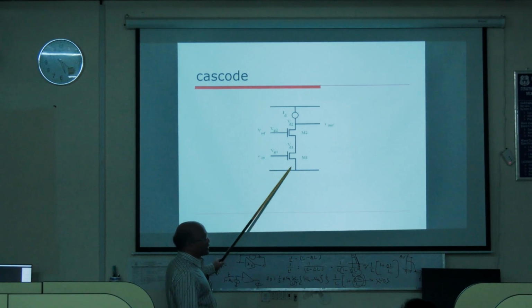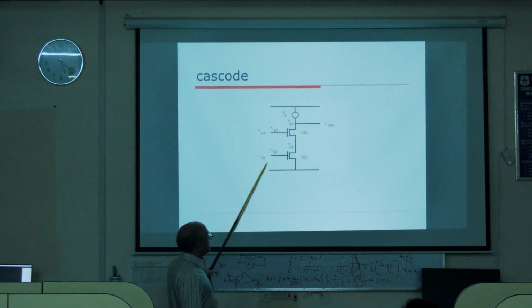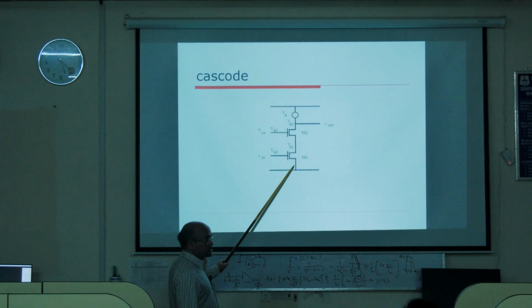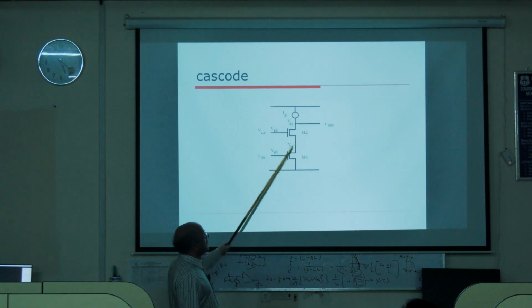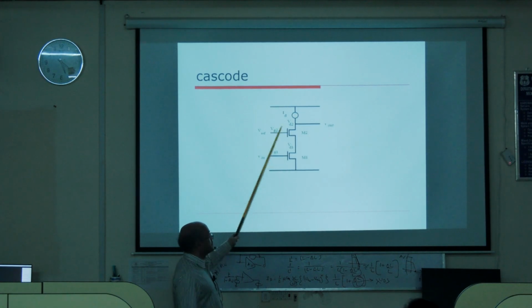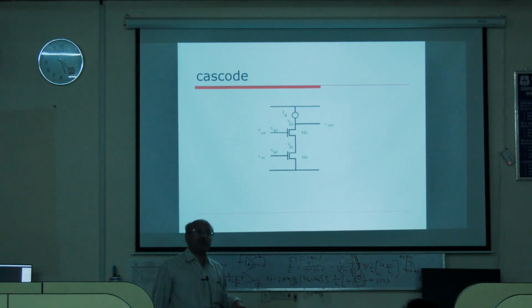Now what we would like to see here is, when you treat this as a single fictitious transistor, the input voltage is at the driving transistor and the output is being taken here. So this is a single transistor. Now, dou ID by dou Vg1 is going to give me the transconductance of that single transistor, Gm effective we call it.